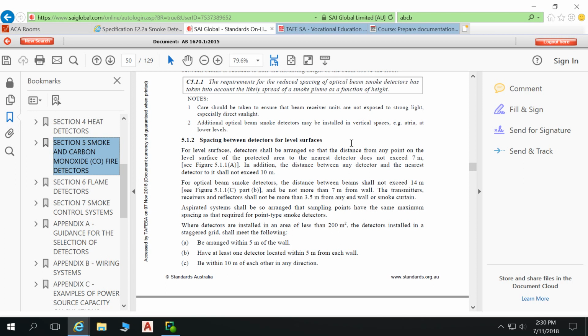plan. So do the life safety plan, which is about distances to exits and specified exits, and then I forget what it's called exactly in the project, but the fire systems. Fire safety plan. Is it fire safety plan? So fire safety plan. So in that fire safety plan, that's also just required for level 1 for this project. And so on that, you'll be putting in any fire extinguishers, any hydrants and hose reels, any fire signage, and any fire warning systems. So do we need a sprinkler system or not?